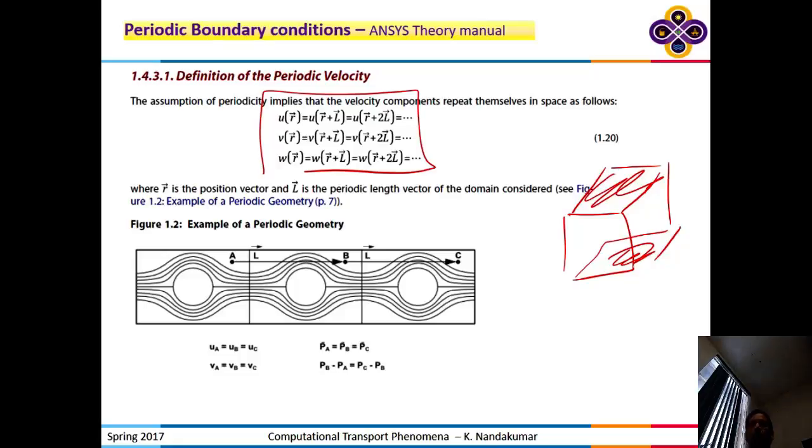And so what happens is you can impose periodicity, and people have done that, and then try to extract the statistical behavior of the flow to characterize turbulence. Okay? But you cannot extract structures that are larger than the cube because you don't have them. And it can produce structures that are smaller because the mechanism is there to transfer energy over all scales, so from the large scale to smaller and smaller scale.